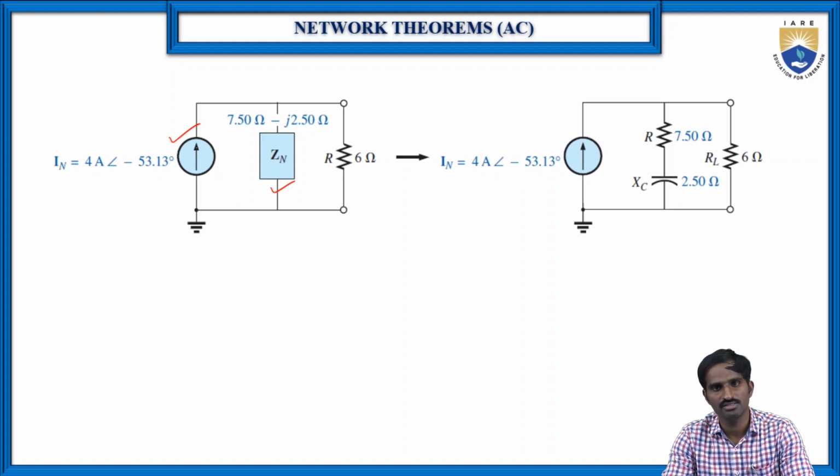But in case of Norton's theorem, we are replacing the load resistance with a short circuit and we are finding the current through the short circuit, so that's why this is also called the short circuit current or the Norton's current. And when coming to the equivalent circuits, in the Thevenin circuit the three components, V Thevenin's, R Thevenin's and the RL load resistance, are connected in series.